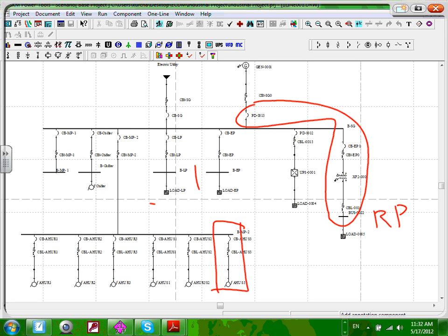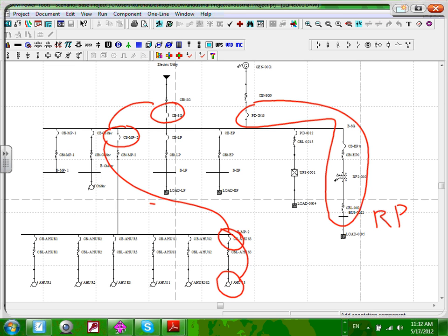Well, let's just do the overcurrent protection devices. So look, that's another nice coordination. If anybody wants to do it, it's optional. Here's the air handling unit. Here's the overcurrent protection device for it. Here's the main for the mechanical panel too. And here's also the main. So these have to be coordinated with each other. All these devices have to be coordinated.